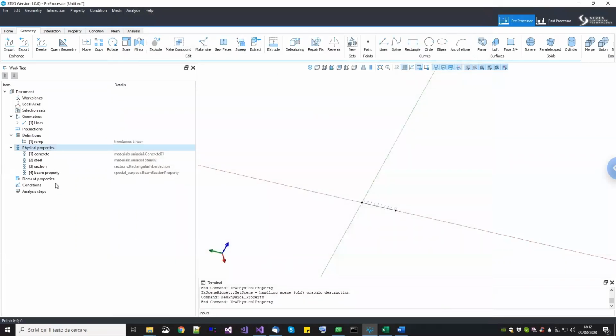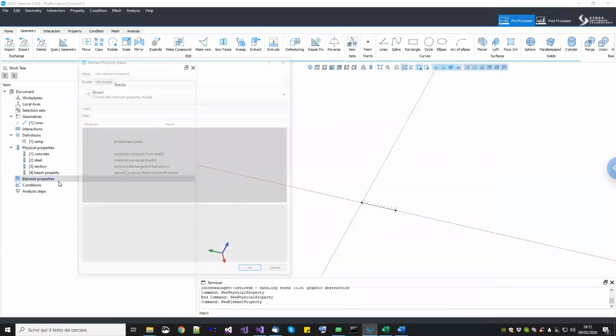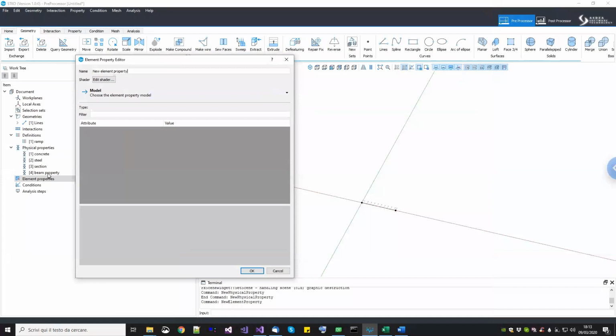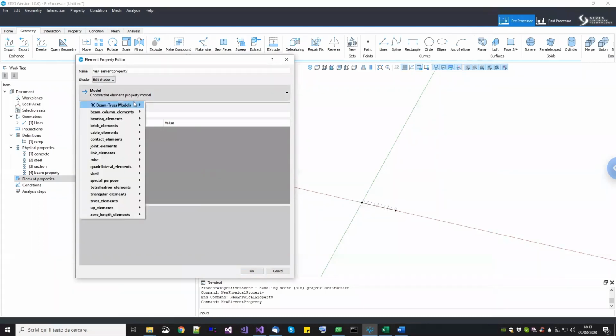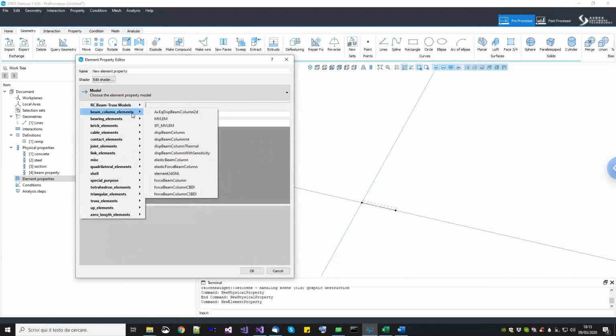Okay. Now for the element property, here there is a note. Since we are forced to use 2 cross sections here, 2 integration points, make sure in this example to use the displacement-based model, because the displacement-based model will localize in the entire element, while the force-based will localize only in one of the integration points. So the response will not be what we expect.